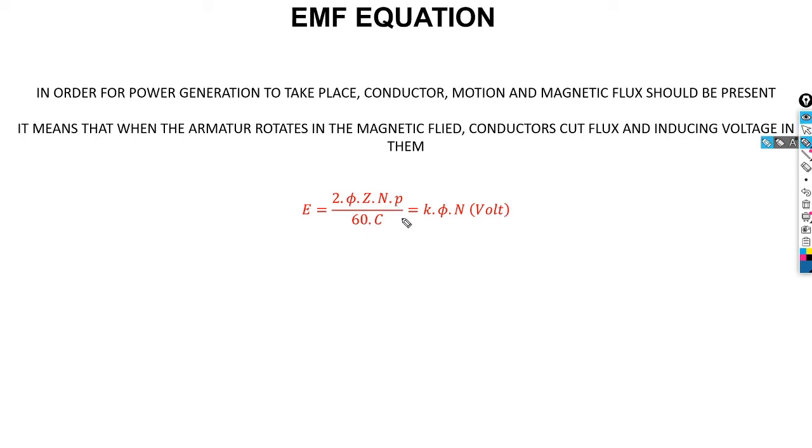Remember the C we were discussing last time, the type of winding. We talked about lap winding, and then we have wave winding. So in the problem, when they state wave, you should know that with wave, I'm expecting C equal to 2. When they say lap, it is going to be equal to 2P, where P is the number of poles.